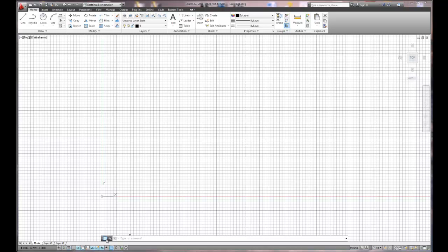And on the bottom, they've changed just a little bit. This is the command prompt line now. It used to be built in as part of the base of the bottom of the structure. It's now a floating menu. We also have tabs on the bottom for layouts and model. Don't worry too much about that initially. In the lower corner, we've got X, Y, and Z orientation, coordinate systems. We have a lot of helper buttons across the bottom. They've added a couple more here in 2013. We're going to be using some of these for our setup here in just a couple of minutes. And then over in the right-hand corner deals with some of the scaling aspects for annotations and locking positions and so forth.